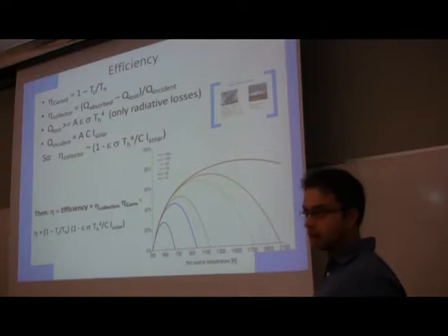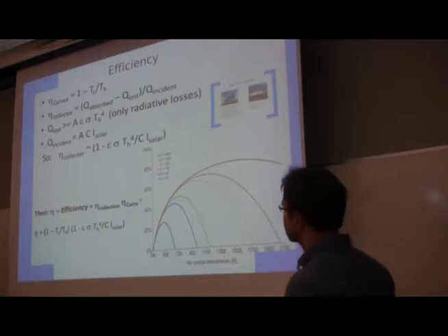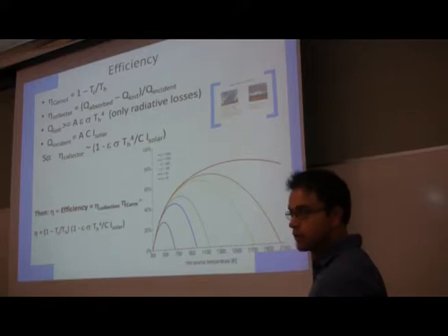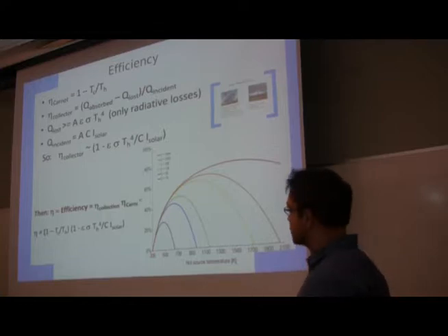I'm making it very general. Obviously, if you have a solar cooker, it's into the cooker, within the confines of the cooker, and so on and so forth. This is multiplied by the heat engine, which actually does the work. So you have a collector and you have something that does the work. They're two different subsystems, right? So that's why you have an efficiency term for the collection multiplied by the Carnot efficiency.